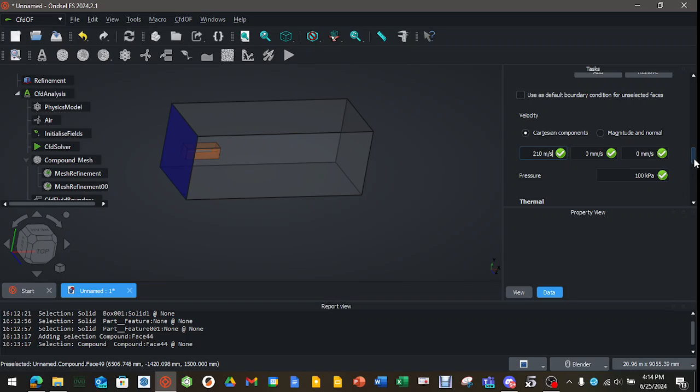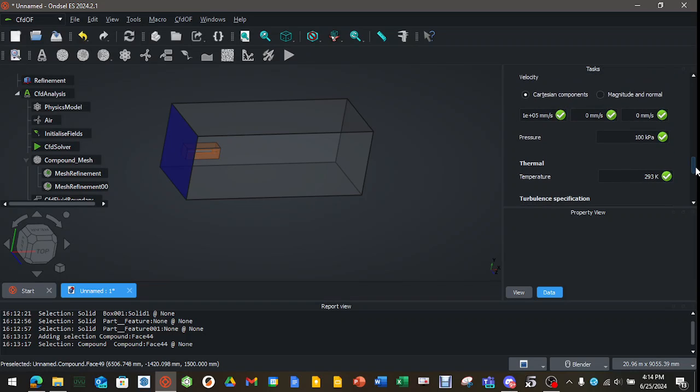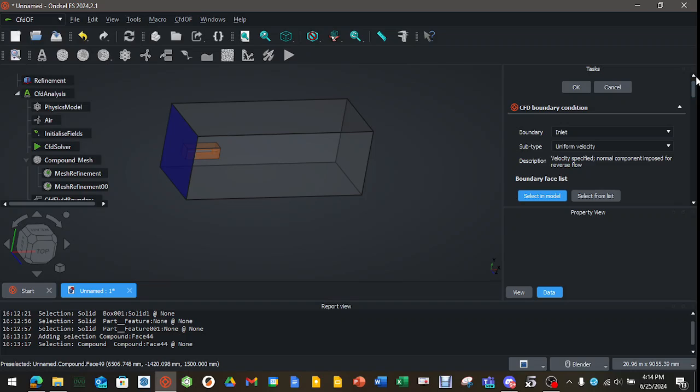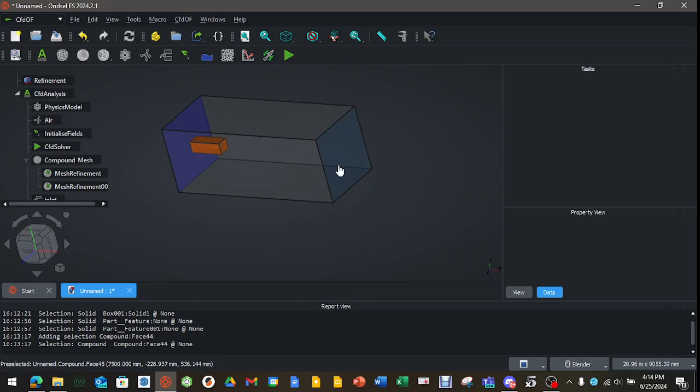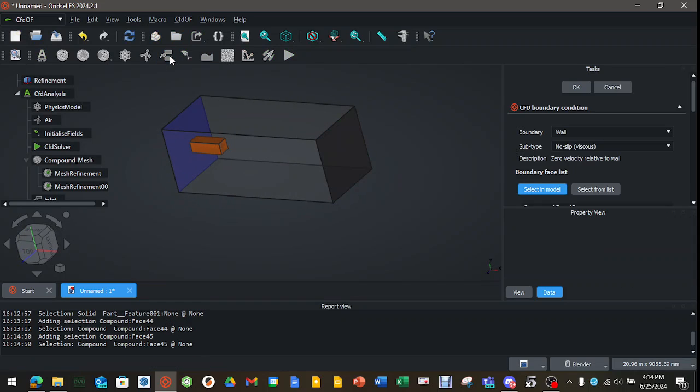The other error, sorry I forgot to mention the second, is as soon as you put in the reporting function to find forces, all your forces will be 0 because the flow cube is not what is being meshed, it's the compound. So basically it's going through nothing there. And it's like, hey, there's no forces here because nothing's here. So okay, hit OK.